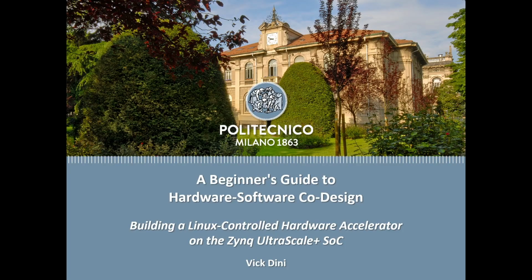Hey everyone! Have you ever wanted to design your own custom hardware and have it talk to a processor? Today we're going to do exactly that. We'll be creating a simple 32-bit adder in Verilog and then building a bridge to connect it to an ARM processor on a Zynq UltraScale MPSoC using an AXI4 Lite interface.